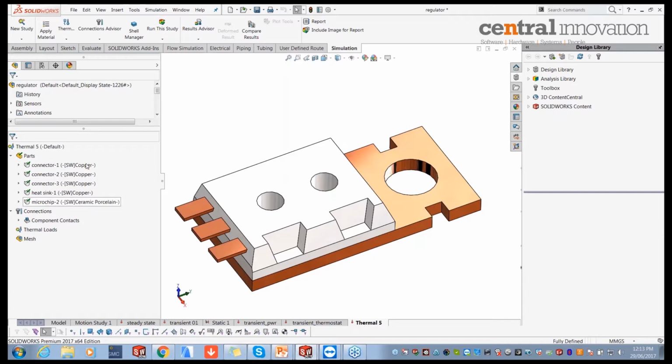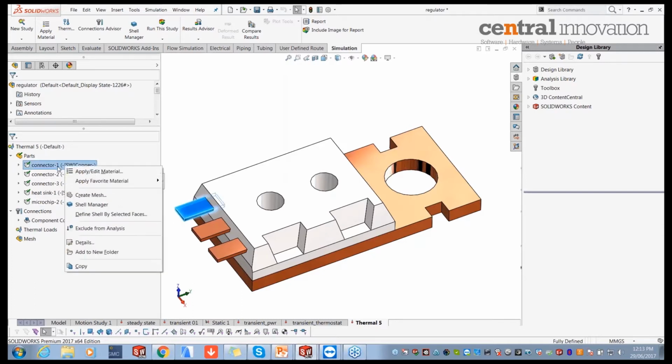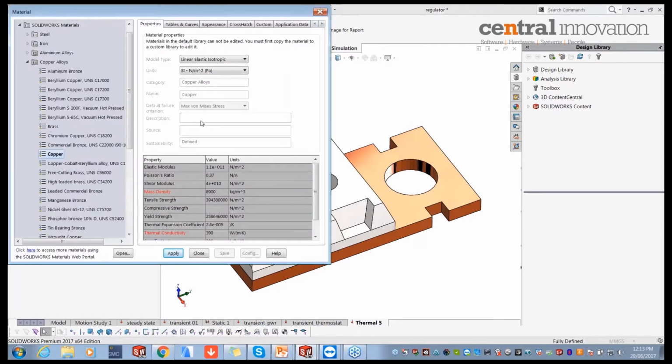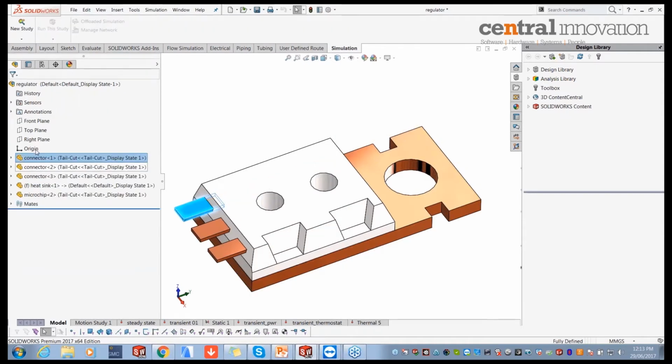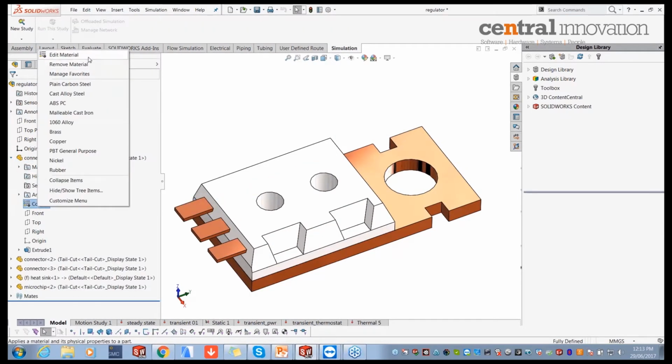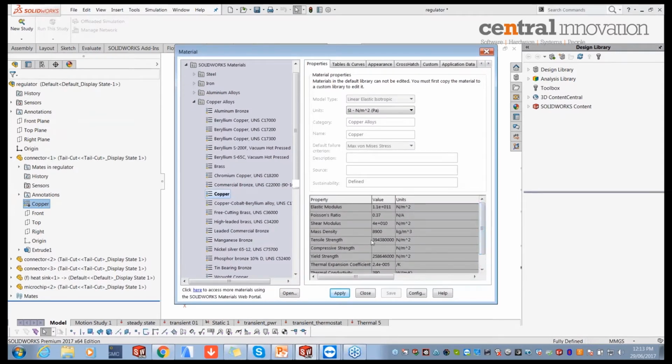material properties directly. And if you have a look at the material properties in detail, I'm going to right click on one of them and go to the standard library. You would notice now SolidWorks has a color coordinator. It uses a different legend to identify what are the most important properties for a thermal analysis. Notice that two of the properties are in red, mass density and thermal conductivity. One of the properties is in blue and the others are in black. If you go to the normal SolidWorks CAD environment and access the material properties, you'll notice everything is in black. So this means something.